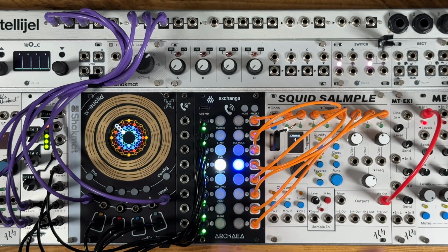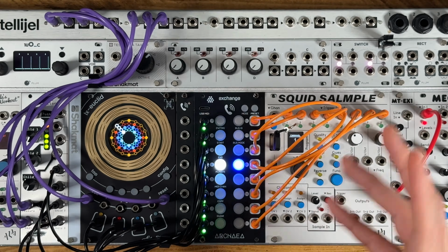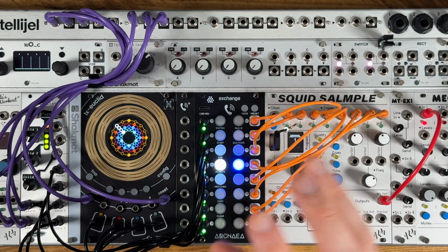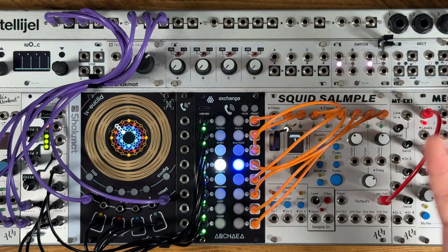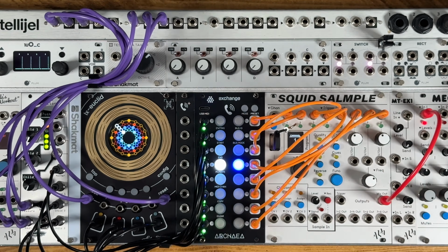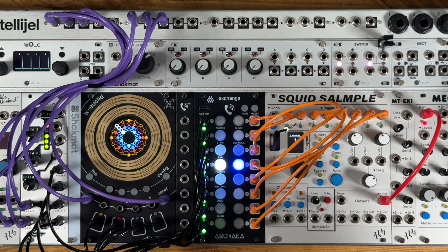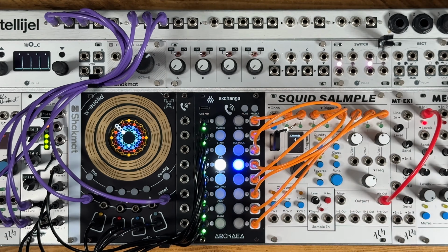You can either skip through them in order, advancing to the next one every time it gets a trigger. You can skip through them randomly with a couple of different random modes, or you can use CV to select which preset is active. And the way that works is it divides a 0 to 5 volt incoming CV by however many presets are in your range that you want to switch between. So for example, if you've just got 2 presets, then 0 to 2.5 volts will select the first one, and 2.5 to 5 will select the second one. As you add more presets to your group, those voltage ranges get smaller and smaller accordingly.